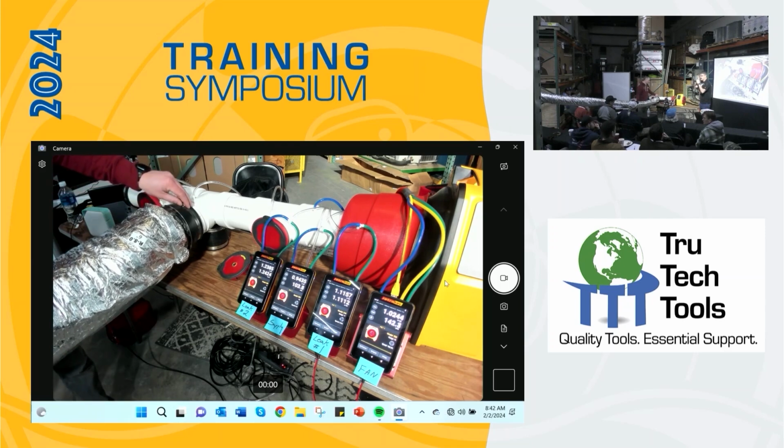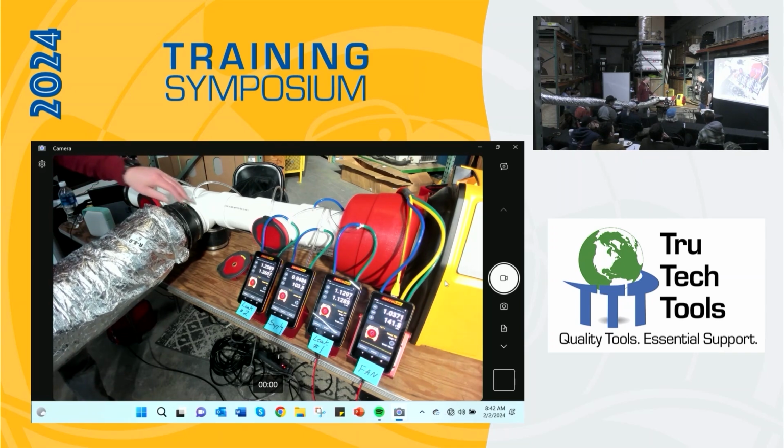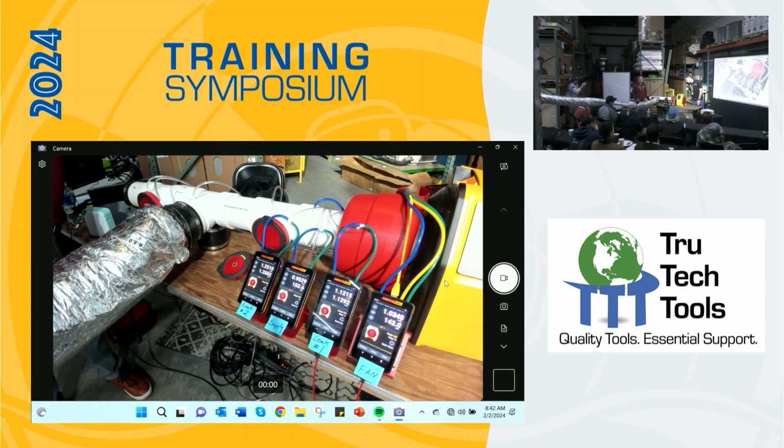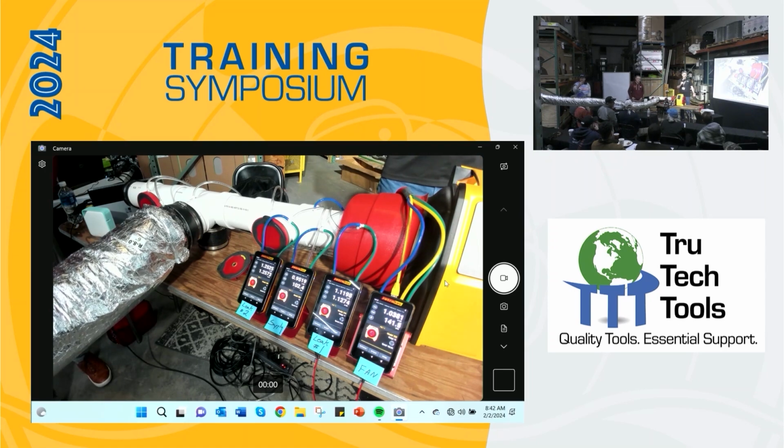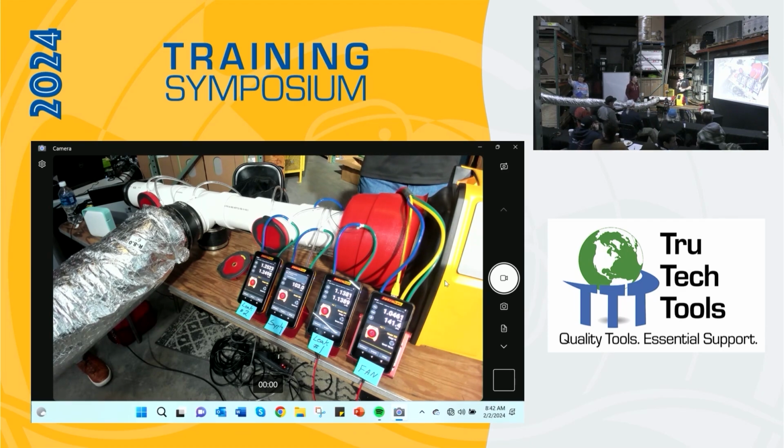Okay, so just by doing that, we've changed that from 97, we're up to 103 CFM, but we dropped our static pressure down to about 0.94. So we're better, still not great, but we're a lot better just by straightening that duct out. And if we pulled that duct really tight, if we gave it a good stretch, I imagine we would improve by quite a bit.